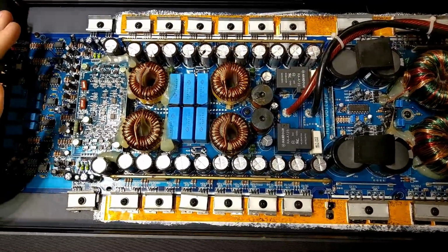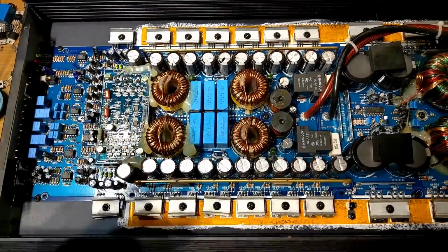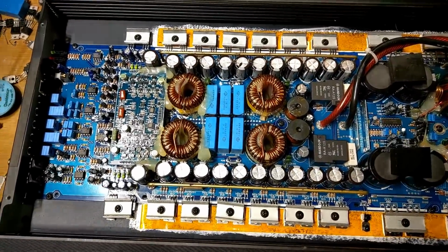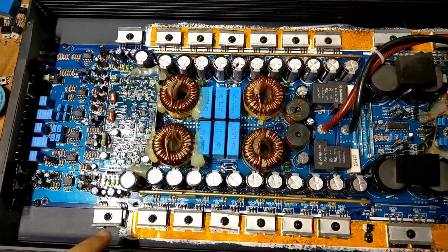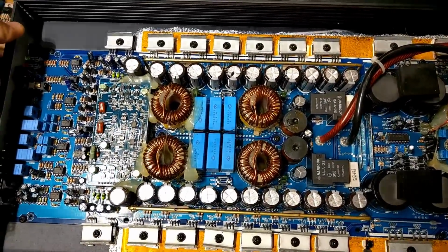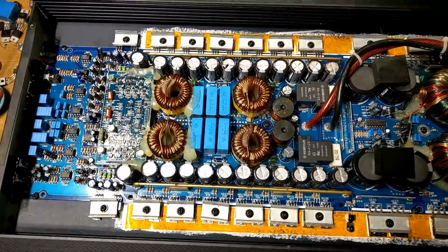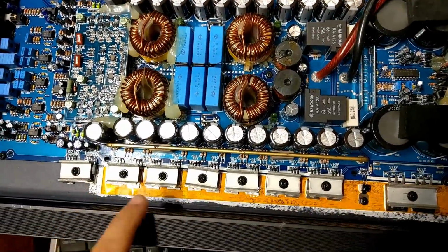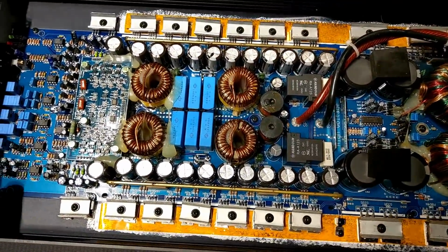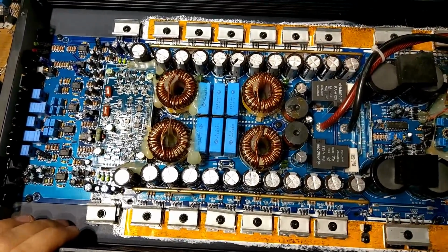Now, these are old Class D amplifiers, and by that I mean they use N-channel and P-channel MOSFETs in the output section. So, although this is only about 2.5K at 0.5 ohm, or about 1800 watts at 1 ohm, this uses a whole load of MOSFETs. This is what I was saying in the videos I've done about the full bridge and new amplifiers, that you can get all this power from just 2 or 4 MOSFETs now, whereas back in the day you needed 24 output FETs for basically 2K. So yeah, very old amplifier, and we're going to get her back up and running today.